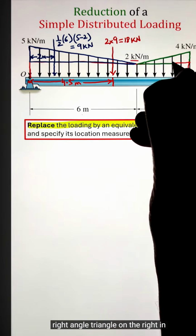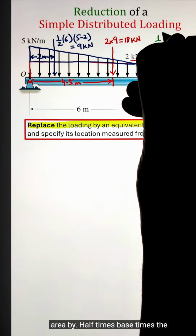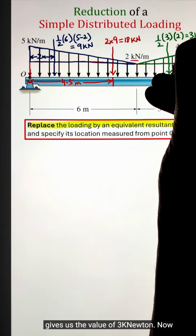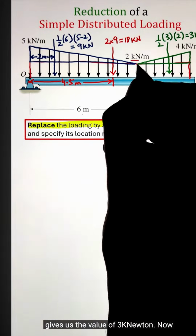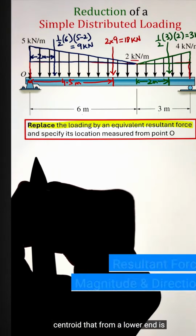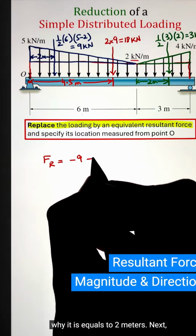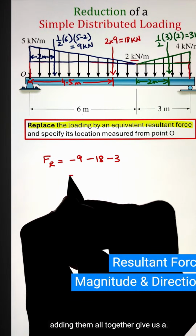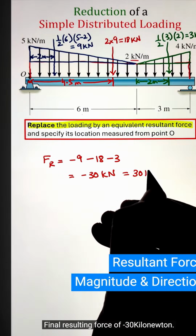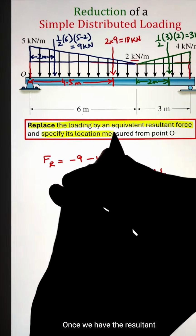Next, I have another right angle triangle on the right, in which we can again calculate the area by half times base times the altitude of the right angle triangle. That gives us the value of 3 kilonewton. Now this point load is acting again at the centroid, which from the lower end is measured by 2/3 of the base. That's why it is equal to 2 meters. Next, adding them all together gives us a final resultant force of negative 30 kilonewton. Here the negative sign is indicating that the force is pointed downwards.